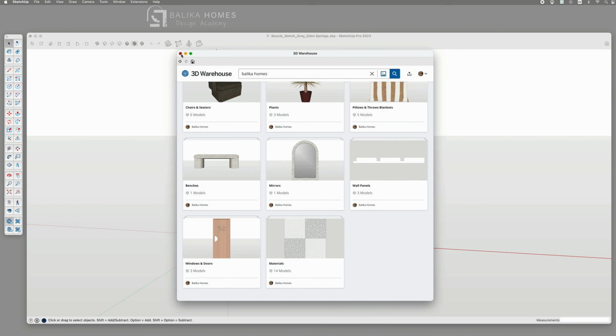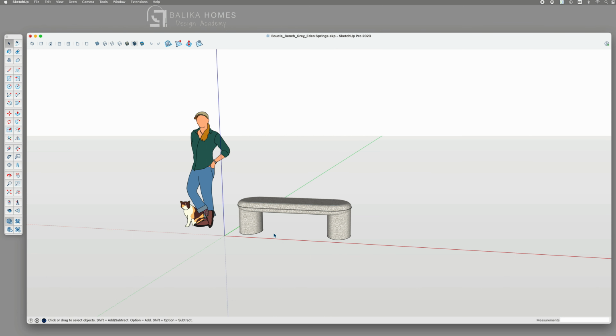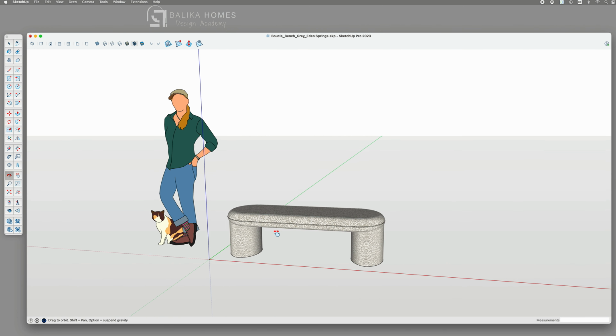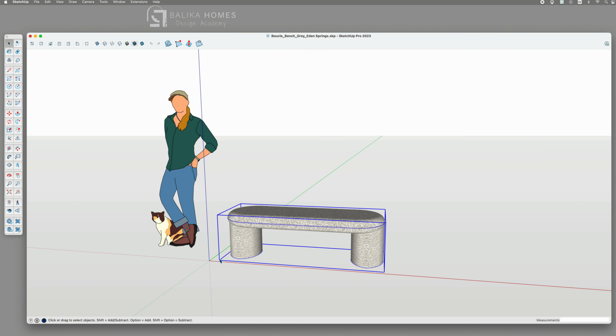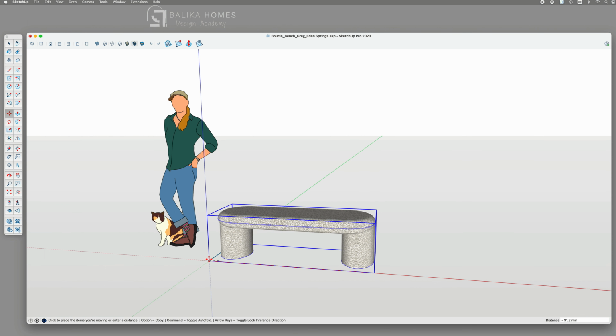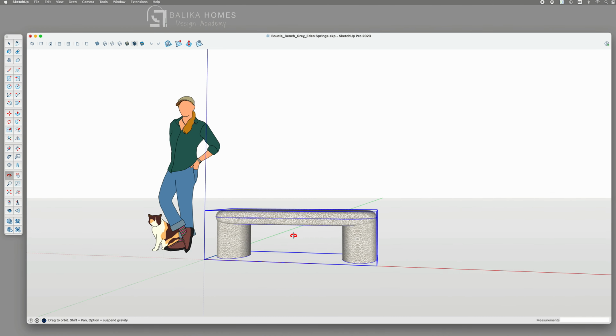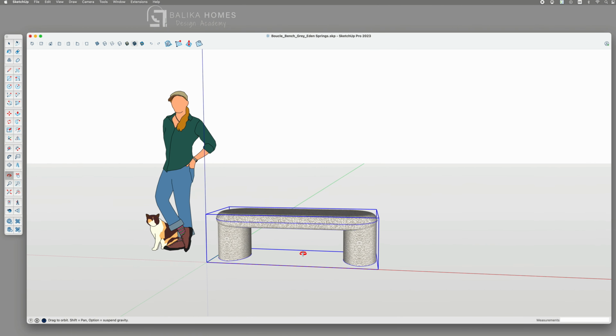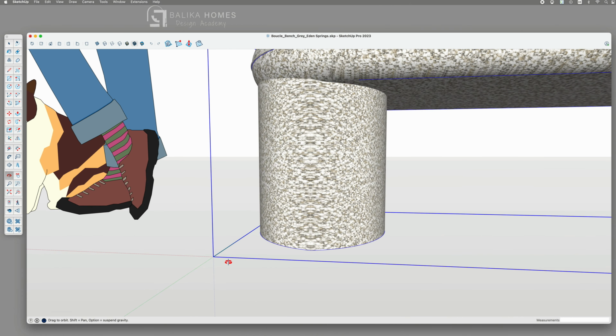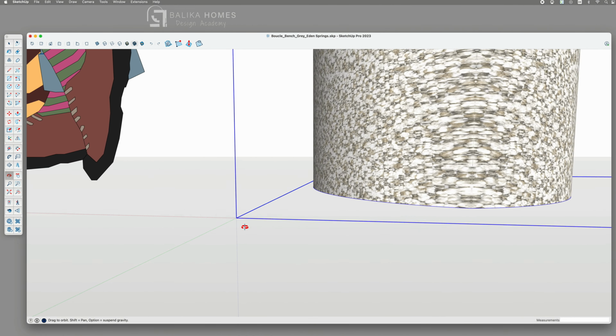Important: always check the scale first when downloading from the SketchUp warehouse. Since some creators start building pieces without basing them on real furniture measurements, they can end up being huge or tiny. The challenge lies in navigating the 3D space within SketchUp, where objects can appear normal-sized no matter if you zoom in or out.